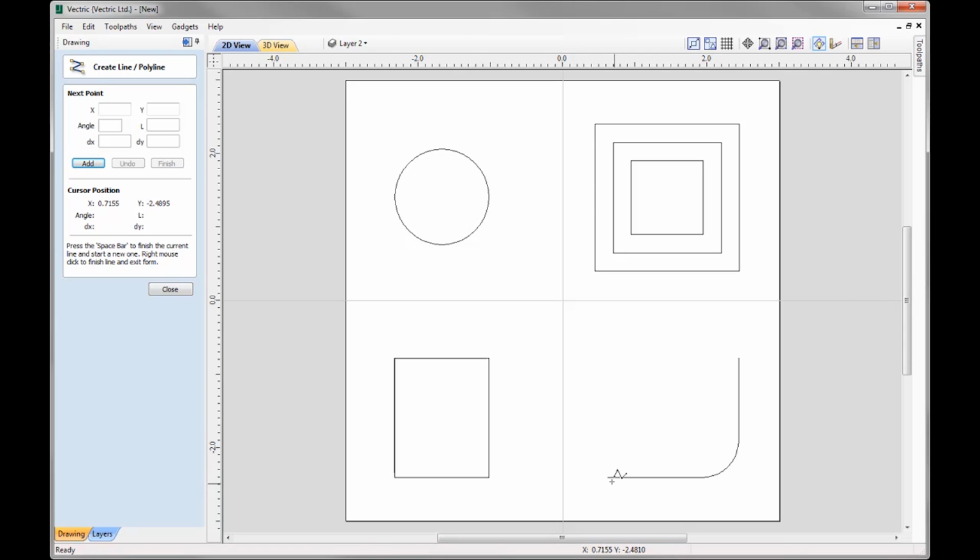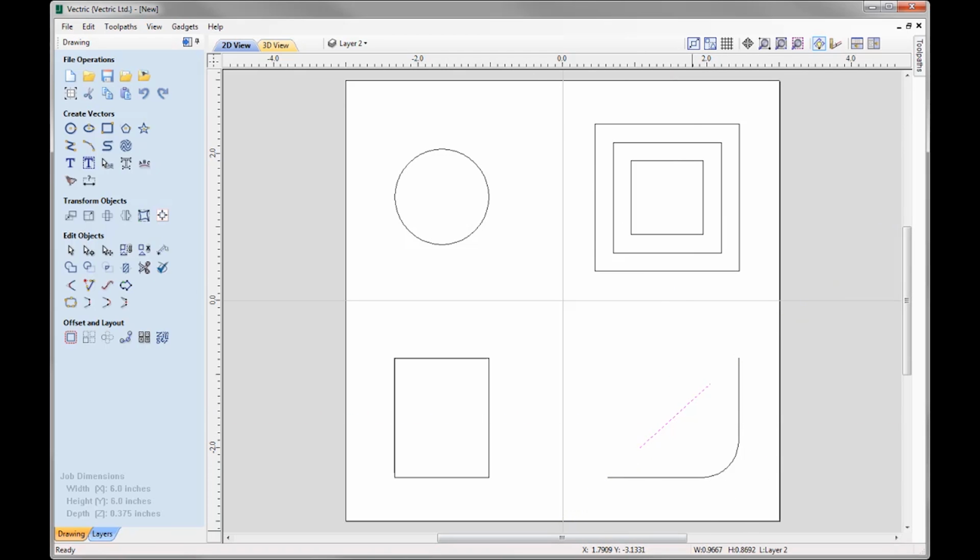For example, wake this point up, bring that along, and you can see that I can find the center of that line, or I could just connect anywhere between the two there, like so. And so Smart Snapping is a very powerful feature for us to create accurately aligned vectors very easily without the need to create construction geometry like you saw in this example.